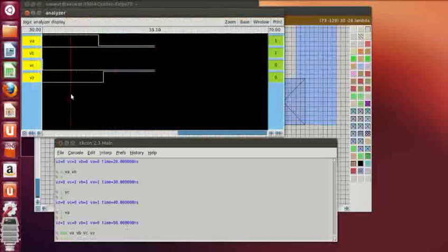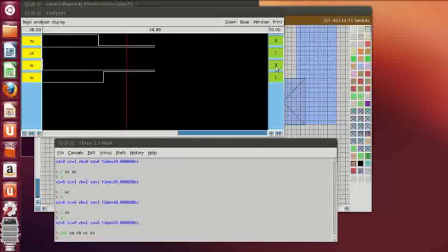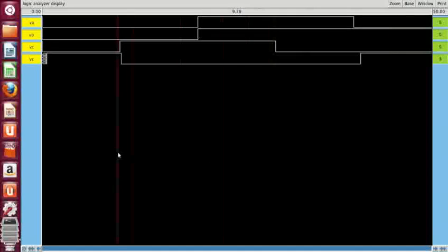So you can see this in 1 1 0, the AND output is 1 and this is OR 0, so the output will be 1. The whole A dot B plus C output will be 1, so the invert is 0. Here A dot B is 0 and A dot B plus C is also 0. So the output is 1. If you want to zoom to full, you can see this is the whole waveform. This is 1 1 1, the output will be 0. This is 1 1 0, output again 0.